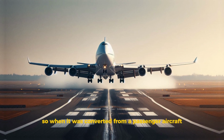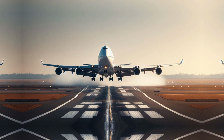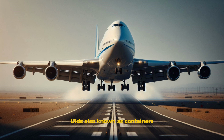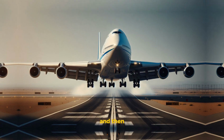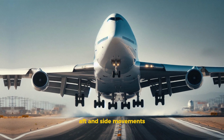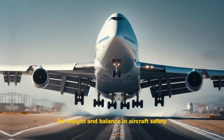So, when it was converted from a passenger aircraft to a cargo aircraft, Telair performed the conversion. They transformed the 747's main deck into a freighter deck designed to house unit load devices, ULDs, also known as containers. The way this is done is that there are rails with ball bearings in the aircraft's floor, as well as locking devices at medium intervals, so you can take one of these containers, push it into nice neat rows, and then flip a little lock switch for each load device. When locked in place, they cannot move, so the load is protected from forward, aft, and side movements. Flying freight requires that the load not move for weight and balance and aircraft safety.